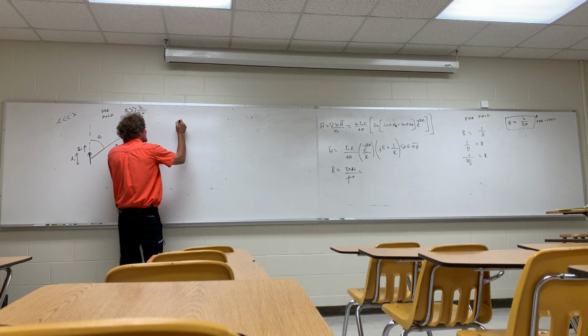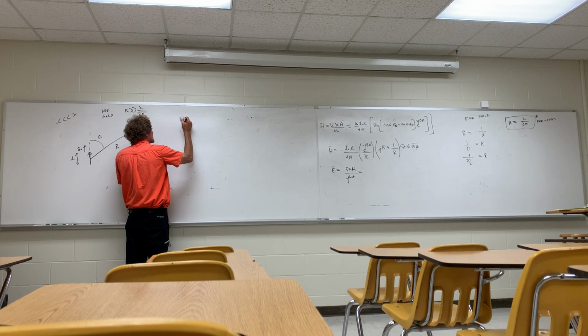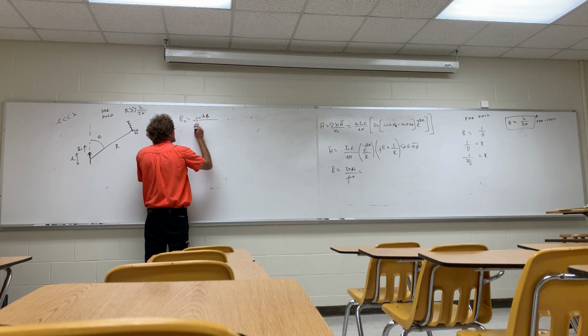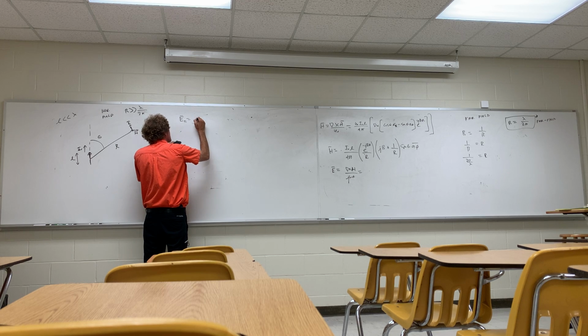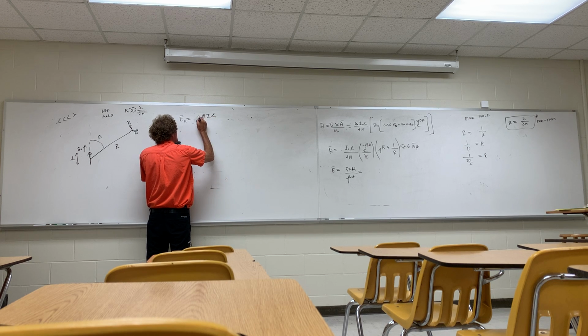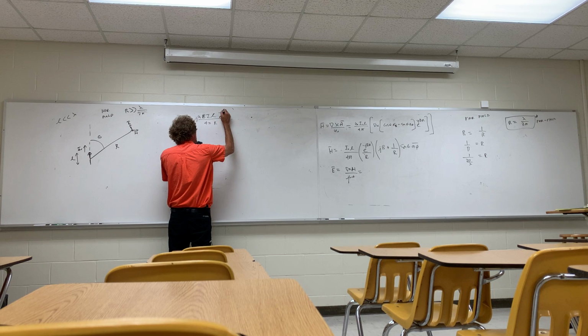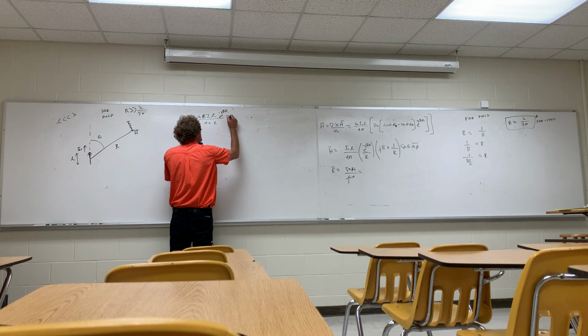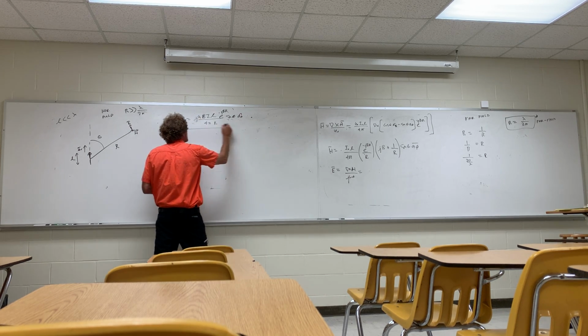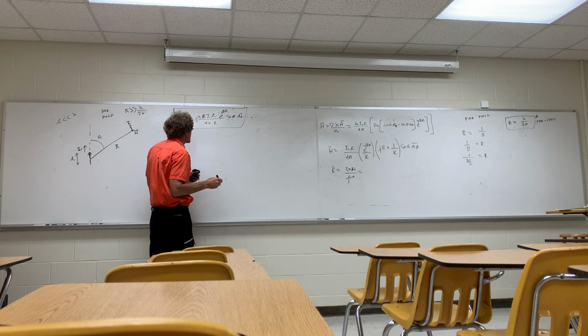That are in the far field. And the E field in the far field, I'm just going to call it E radiated. You can use anything that I identify. That's going to be j eta beta I L over 4 pi R times e to the minus j beta R times the sine of theta in the a theta direction. That's the E field, the radiated component of the E field for a short dipole.